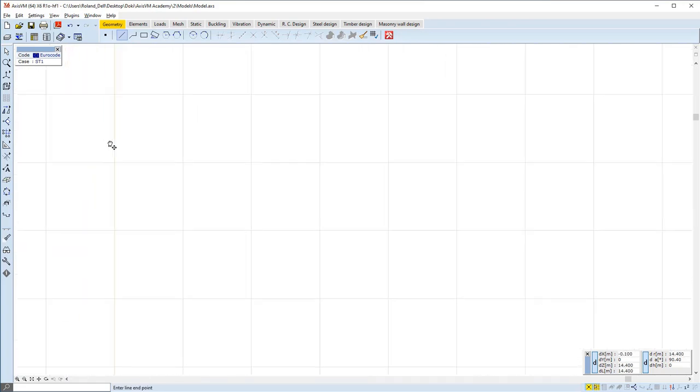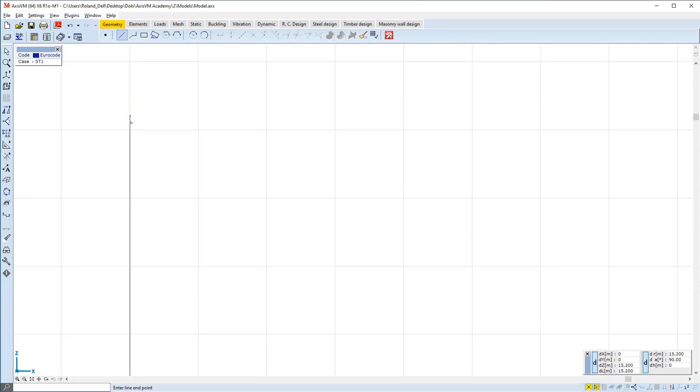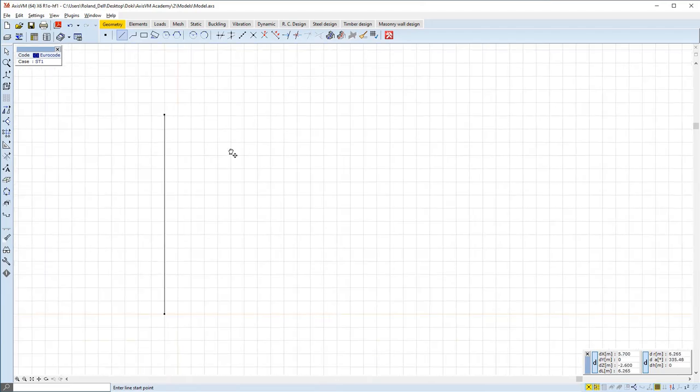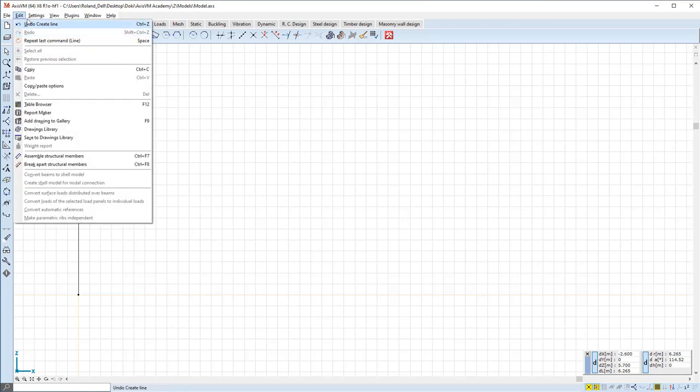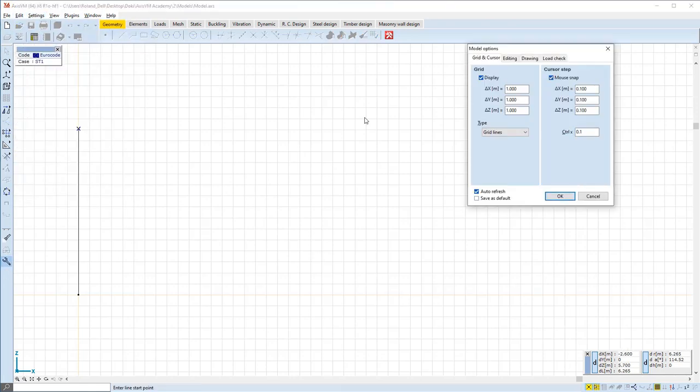Using the graphical coordinate input, the cursor is only able to snap on certain division points of the main grid. These division points are placed in 1/10 of a meter by default, or, if pressing down the control button while moving the cursor, 1/100th of a meter. Each function can be completed with either clicking the mouse or pressing the enter button. Default values of the cursor snap points and the angle constraints can be modified under model options of the settings.